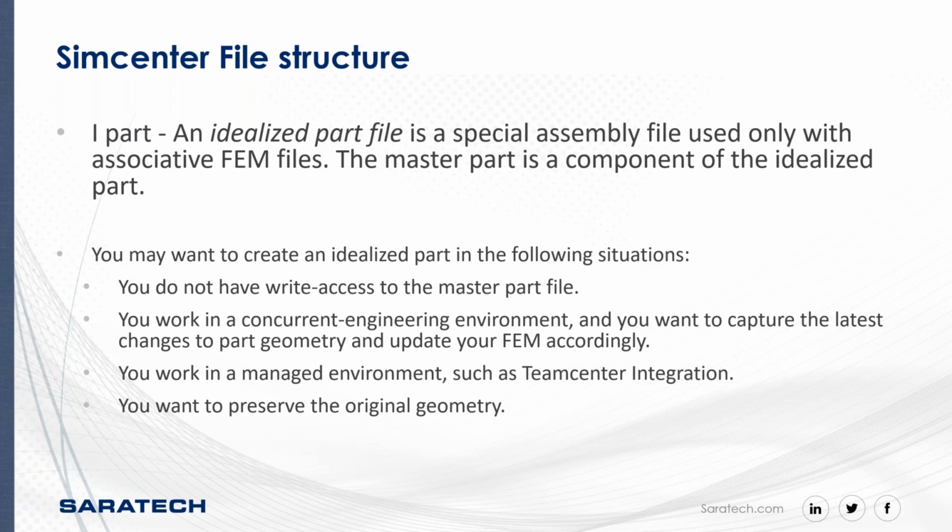So some of the reasons you'll see down here: maybe you're in a managed environment such as Teamcenter, so you don't want to be actually editing somebody else's part, and maybe this is connected to some sort of assembly, and you're just throwing things out. You don't have write access to the master part, maybe you can't even edit it. And what I use this a lot of time for is what if scenarios. Hey, what if I add something, remove something? I want to mid-surface something like in our example. So in the example at the bottom, you want to preserve those original geometries.